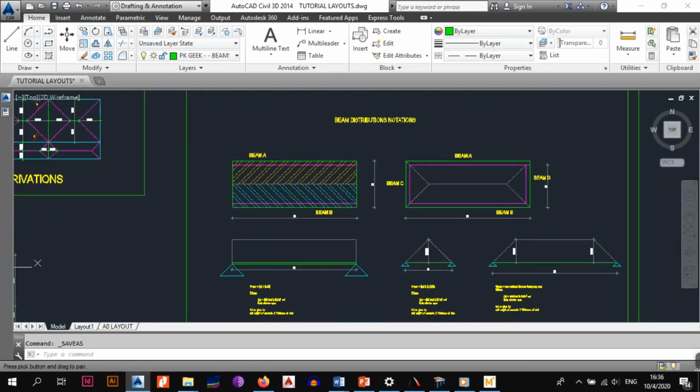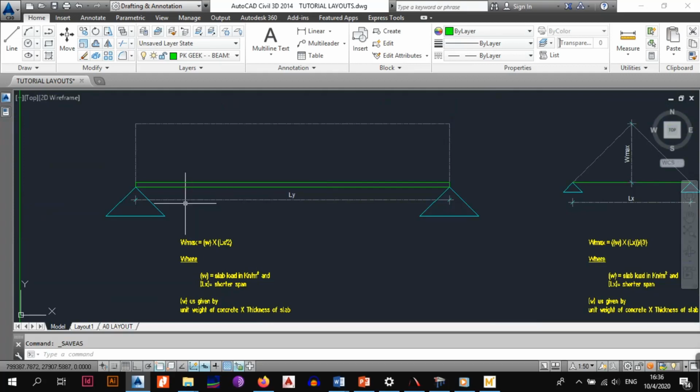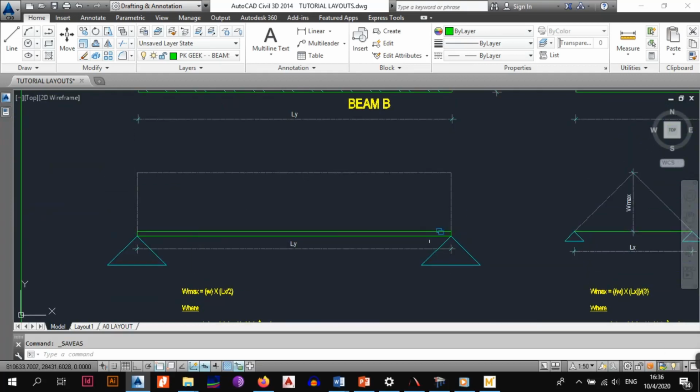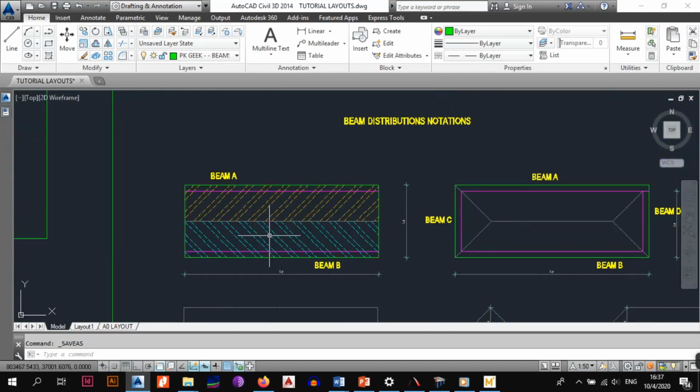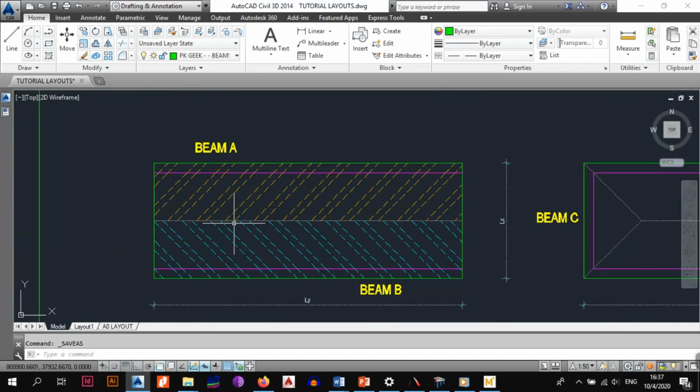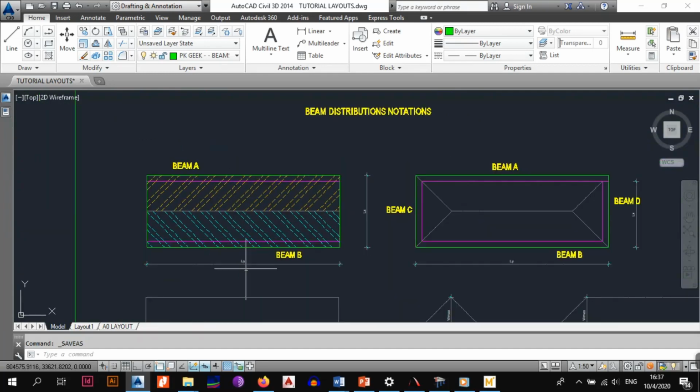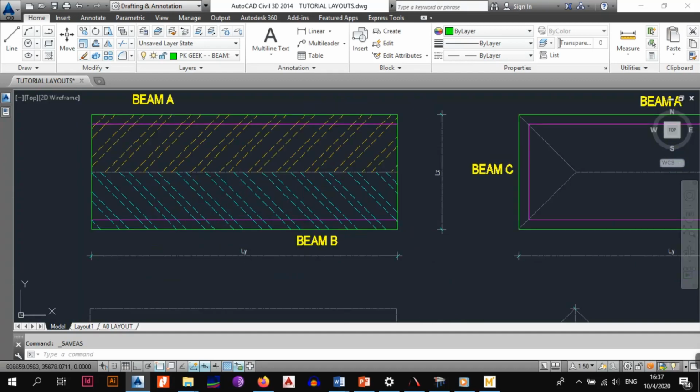For the walls, it's simple. There is a representation. Obviously, your wall is going to be on top of the beam. All you have to do is see the line load, how many kilonewtons per meter the wall will distribute to your beam as you flow throughout. Now, we need to look at slabs. In the case of slabs, there are two conditions. You could have a one-way spanning slab, as you can see right now.